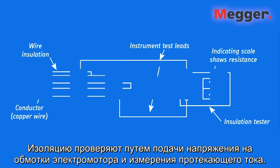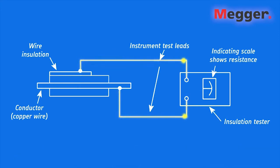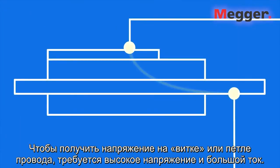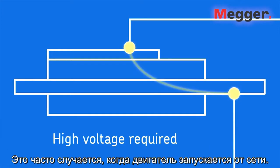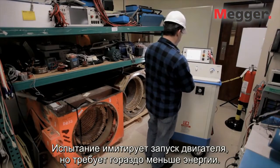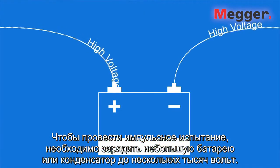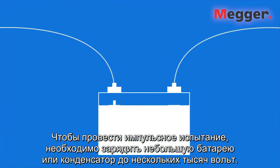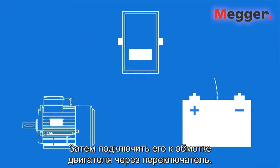Insulation is tested by putting a voltage across the insulator and measuring the current flow. To get a voltage across a turn or loop of wire requires high voltage and high current. This often happens when a motor is line started. The surge test simulates a motor start, but with much less energy. In concept, to run a surge test, charge a small battery or capacitor up to several thousand volts. Then connect it to the motor winding through a switch.